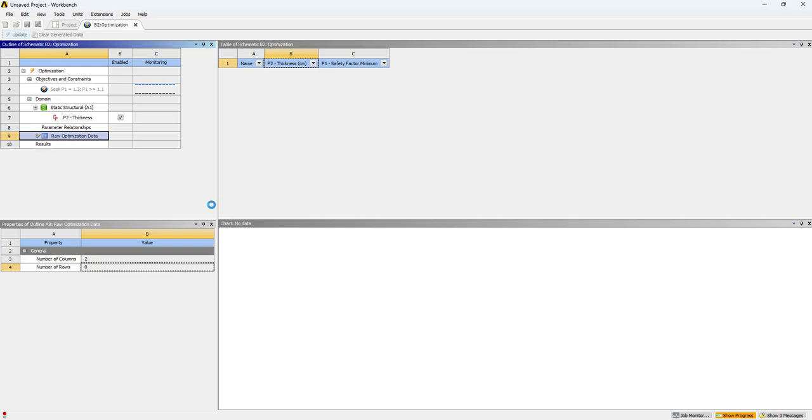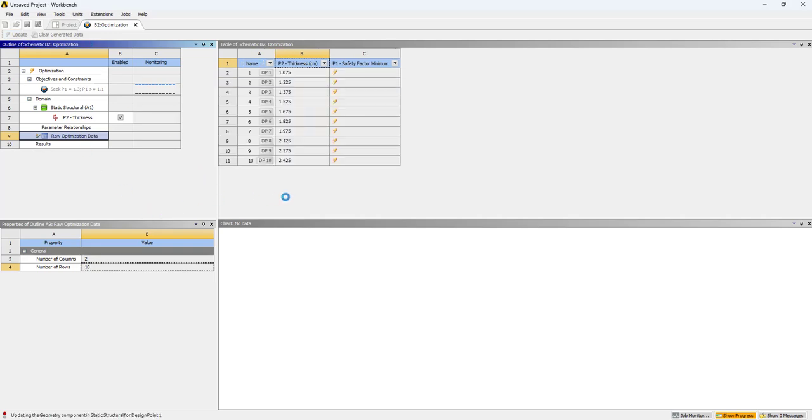are acquired. So after clicking on update button, ANSYS will generate the design space based on the settings and will solve the problem for each of this design space automatically, and then recommend the top 2 or 3 candidates based on the settings. Let's wait until all of the solutions are run and we get the results.